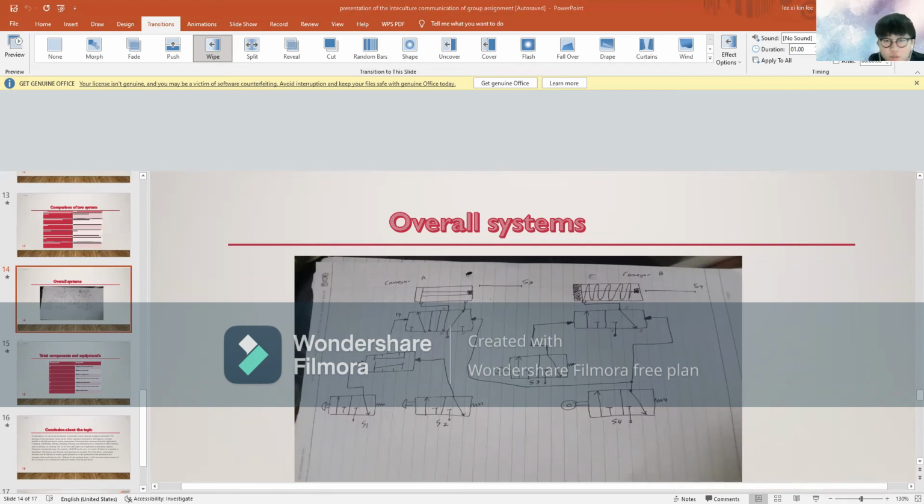Let me explain the operation of this system, which is a combination of two conveyor systems. I would like to have a simple talk about how this system works. As in a factory, safety is very important for the worker, which made me use the AND logic in the first system, which needs two push buttons to be pressed at the same time.